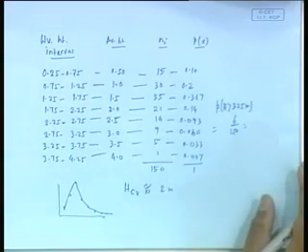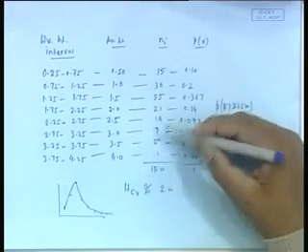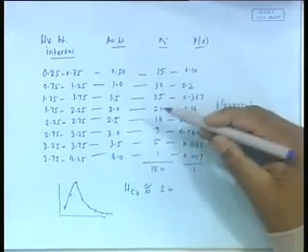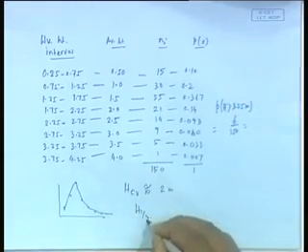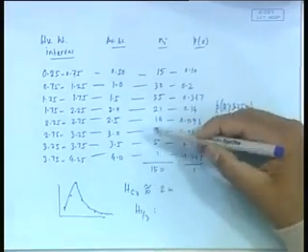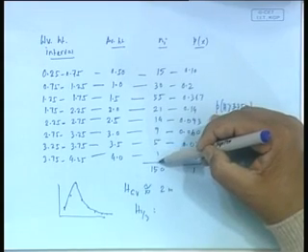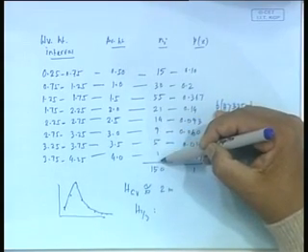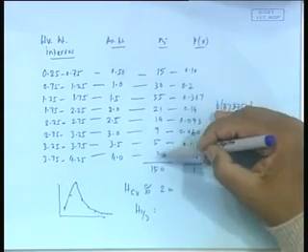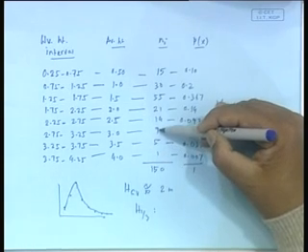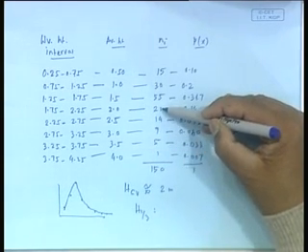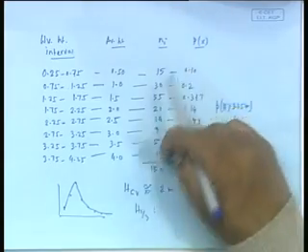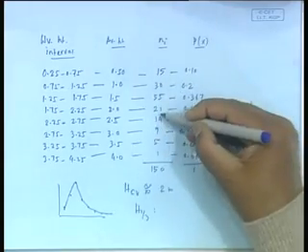Now, the important point is how to find, let us say, H 1/3. How do I do H 1/3? This confusion comes sometimes. I need to take from here the average of the top how many? 50. Now, count it: 5 plus 1 is 6, 6 plus 9 is 15, 15 plus 14 is 29, plus 21 is 50. Actually, this example that I took is becoming exactly 50.